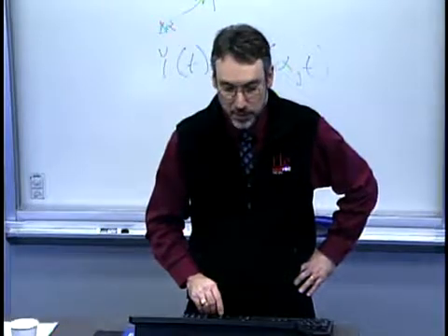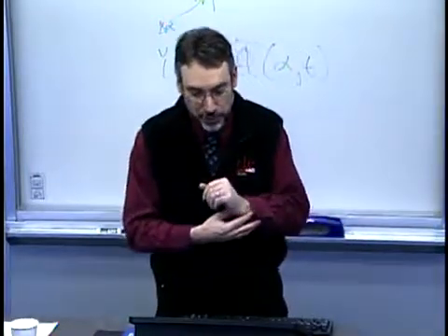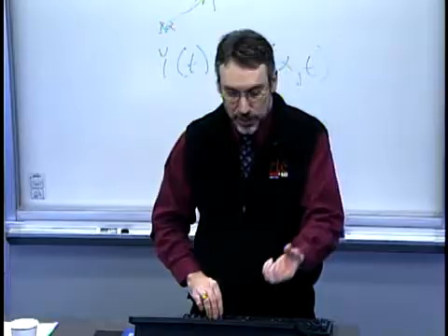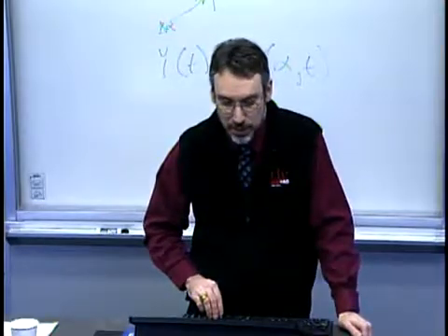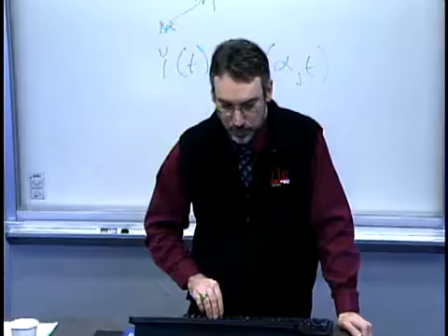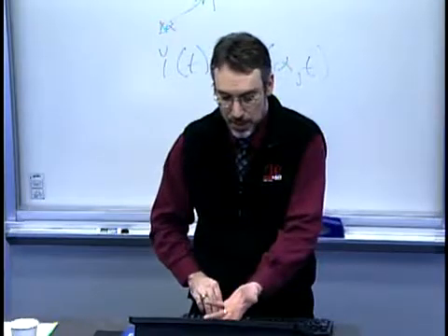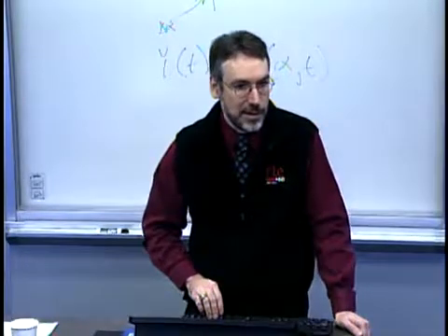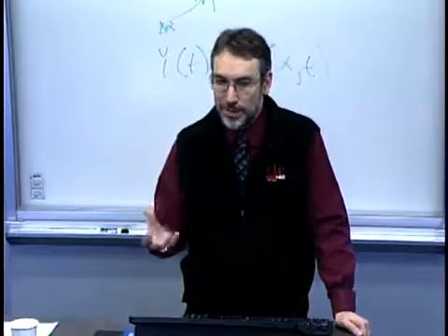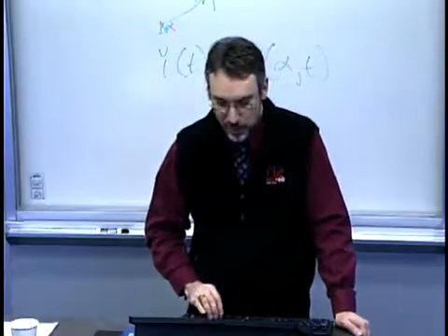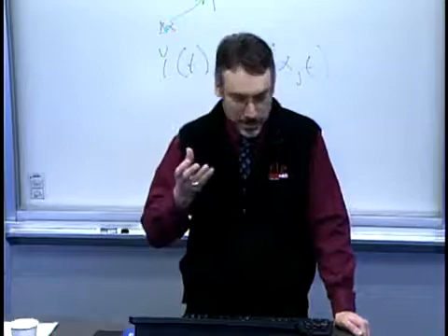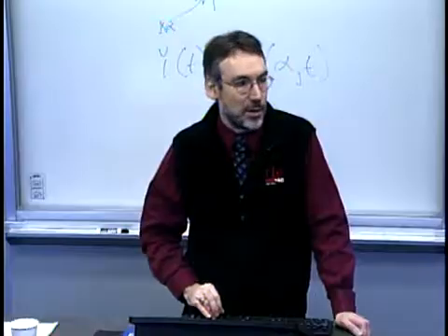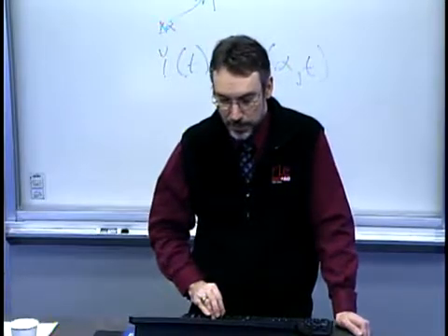Okay, so let me go to one more. Here's another one. This is break bending of a metal sheet. And the basic idea in this process is we're trying to change the geometry under the application of force in a bending process. So we might have some tooling. We have some piece of metal, say, and we press down. And the intent is to create some permanent deformation in the part. An important component here is that when we remove that force, remove that pressure, there can be spring back in that part.